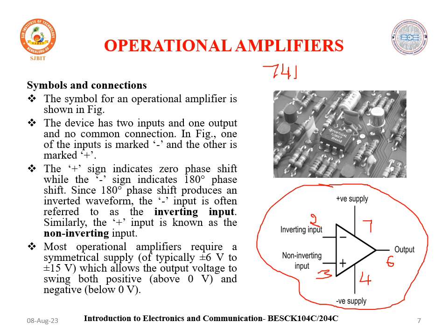In this circuit symbol, we consider the operational amplifier as having two inputs, an inverting input and a non-inverting input, and one output. The inverting input is applied to the negative symbol, and the non-inverting input is applied to the positive symbol. Then there are two supplies, positive supply and negative supply. We can call them plus VCC and minus VCC. Up to 6 volts to 15 volts we can apply.